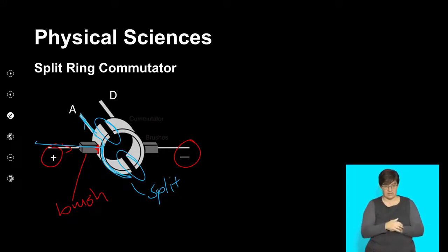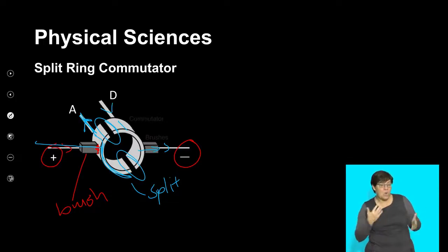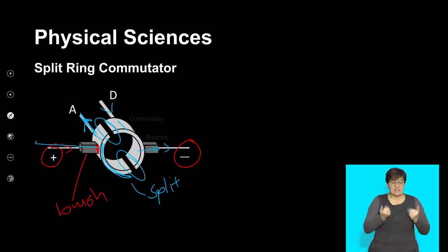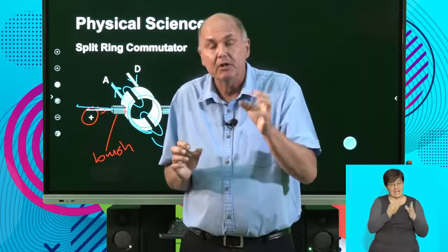And so the armature at that point is point A, the current is going to go into A. And if we look at the reverse part, the current is coming out of the negative. It's going to come out of D. It's going to convert into the commutator, that second part of the commutator, through the brushes and back to the battery. So that's how this process works, of supplying each part of the coil a different direction of current.